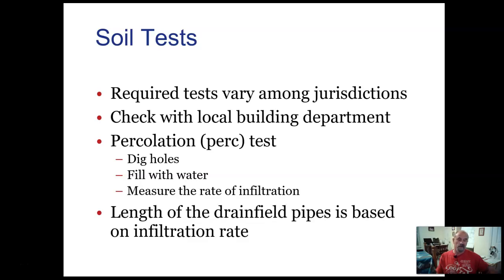Perk tests have been found to be unreliable in certain cases, especially during a season of heavy rain or heavy drought. Many jurisdictions no longer even allow the use of perk tests to determine infiltration rates. They make it mandatory to bring in certified soils in order to put in a new septic system.